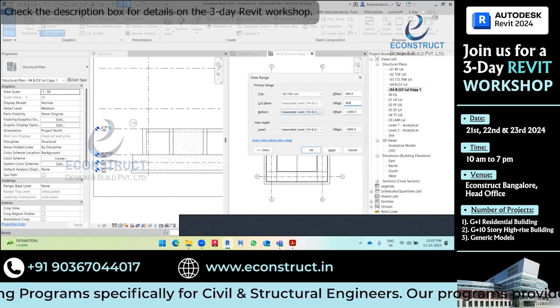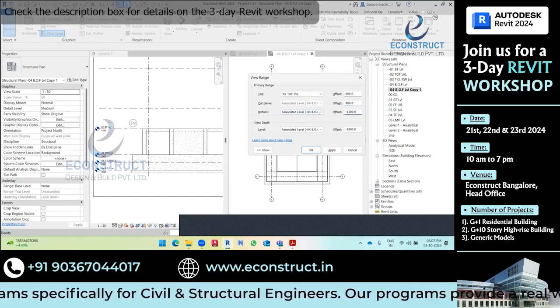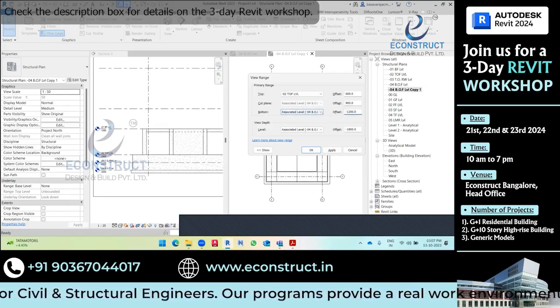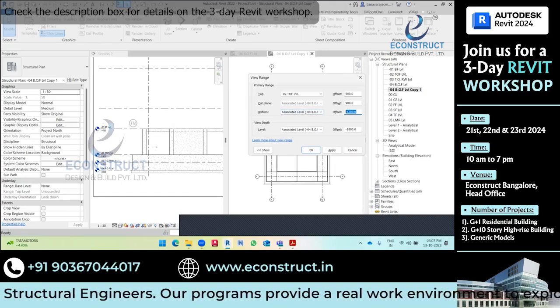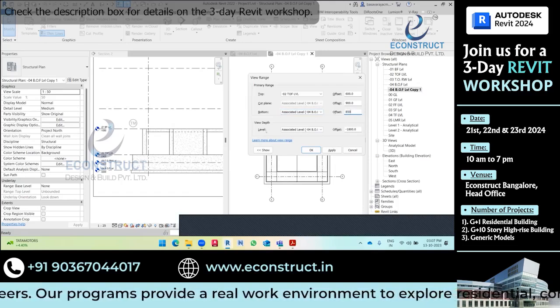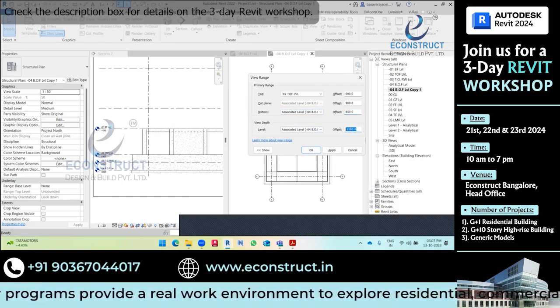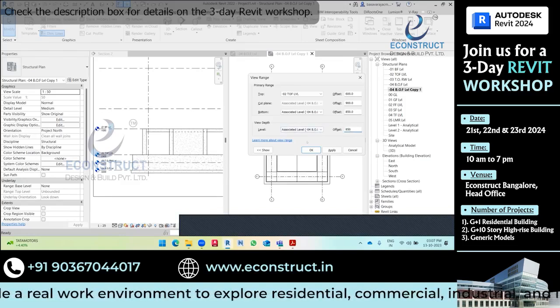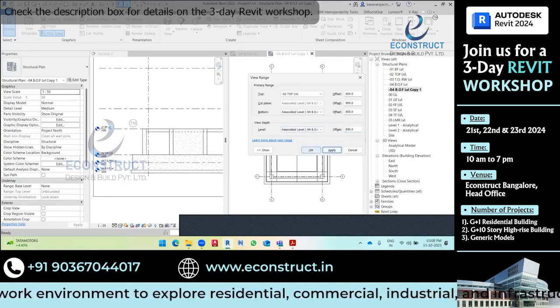Bottom level, instead of minus offset, I will give the plus offset only, like 850. And view depth, I will make it 850 only. Apply.